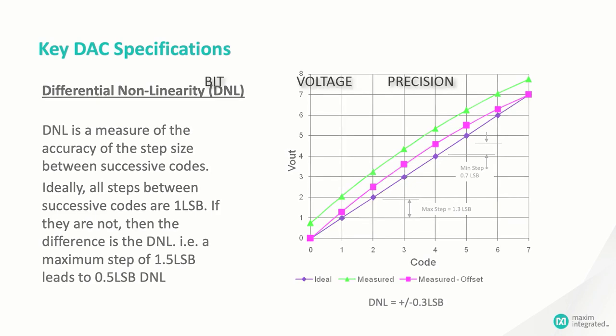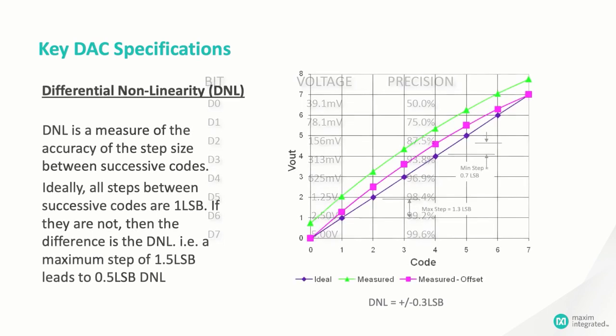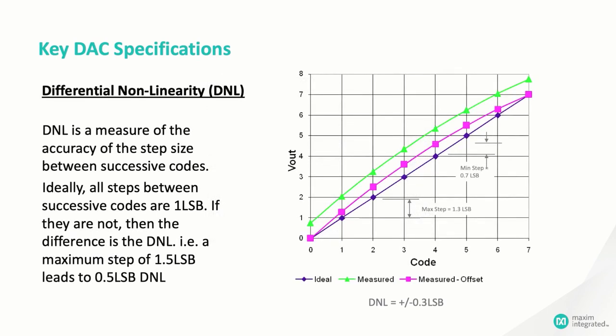See, the voltage contribution for each bit has to be twice as precise in percentage terms as the next lowest bit. In our 8-bit example, the LSB switched 39 millivolts on and off. But the MSB switched half the full-scale voltage, or 5 volts, on and off, and that 5-volt output had better be precise to a fraction of the LSB output, which means the output has to be significantly better than 1% precise, and that's just for a cheesy 8-bit converter.